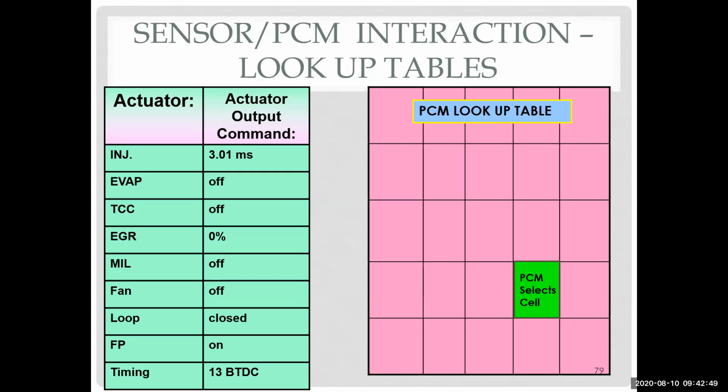Different tire size as well as the different air level in the tire affect every percentage. Yeah, everything is very sensitive. A lot of money goes into engineering these systems, and when we start playing with things, we don't always know what's fine, what they allowed for, and what's catastrophic or what causes a real weird problem. So when I'm diagnosing a car, one of the things I do with my visual inspection is look to see are there any aftermarket components on the car? In other words, has anything been changed on this vehicle to make it no longer stock?